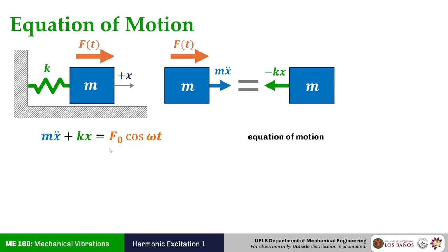Here in this case, we have a linear system. Again, for now, we'll take off damping to make things easier. Here you have a mass and a spring that is restraining the mass. And what's new here is that you have a disturbing forcing function f of t that is making the system move. If you convert it into a free body diagram type of equation, you end up with this form. And if you move around variables, you will get this equation of motion.